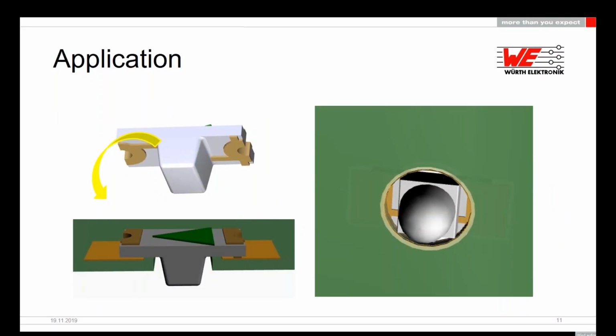The reverse mode LED, as its name says, is designed for applications whereby the light shines down toward the board instead of up. Yes, it sounds strange. But for this case, we need to make a hole in the PCB, and the LED can light through it. This could be useful, for example, where the board is used as some sort of touchpad with LED indicator or backlighting, or in applications whereby the light diffuses through the glass fiber in telecommunication.